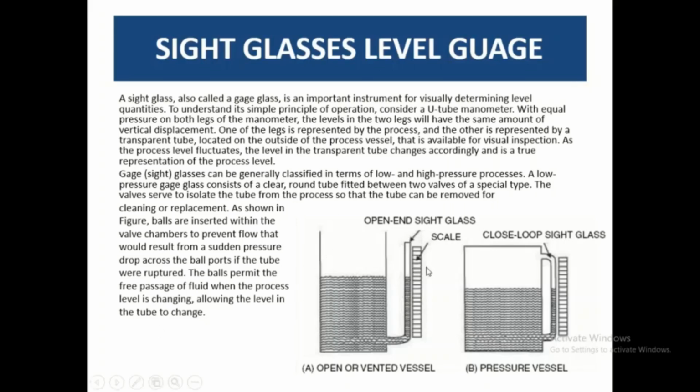for your waste material, you can use these side glasses in order to visualize what the level percentage of these vessels is. So they are open. For open, you don't need to reconnect it with the vessel again. Okay, so this tube is open, and with that we have a scale which is calibrated accordingly. So there you can easily assess what is the height covered by the liquid.